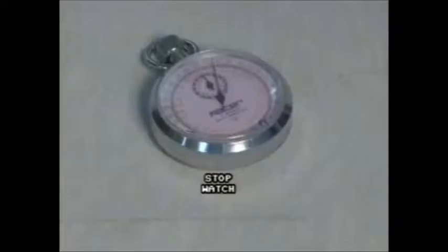There are some procedures you have to follow so that you can perform your test well. You have to find a certain site and dig an undisturbed sample. You bring the sample to the soil laboratory. You make sure that the sample you brought has different grain sizes, so that it will be able to have shear strength. When you get the sample for the test, you make sure that you organize it. Let's now start the test.